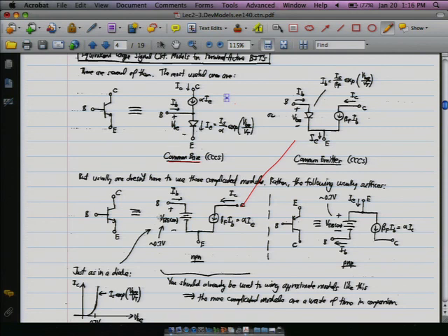If it's much lower, then you're going to have almost no current flow. Your diode is essentially off. If it's much larger than that, your device is going to explode. And I have seen that in lab. You might too over the course of the semester. Some people will pass way too much current through the device, and it'll get hot and pop.